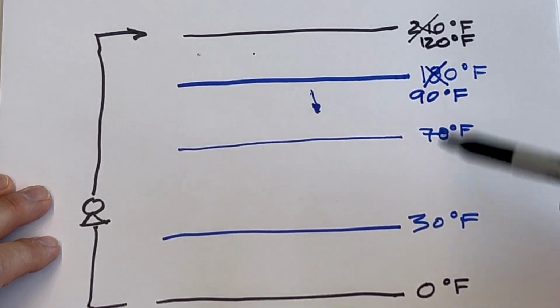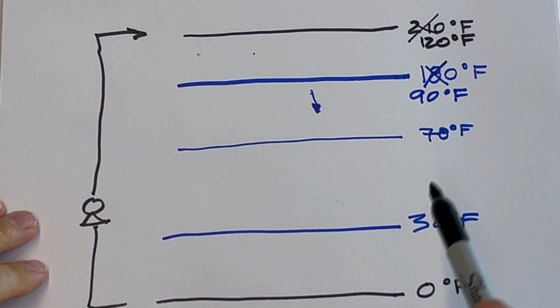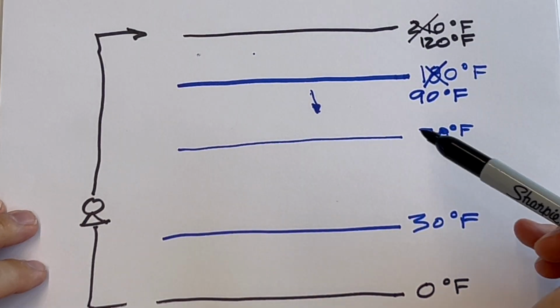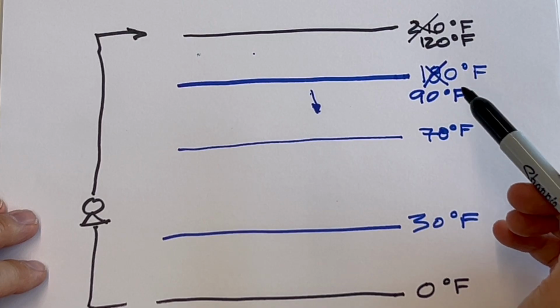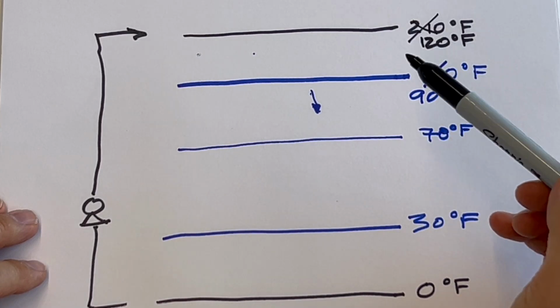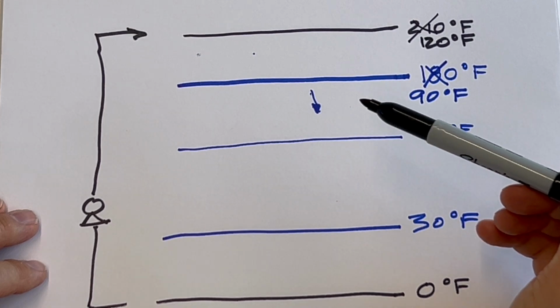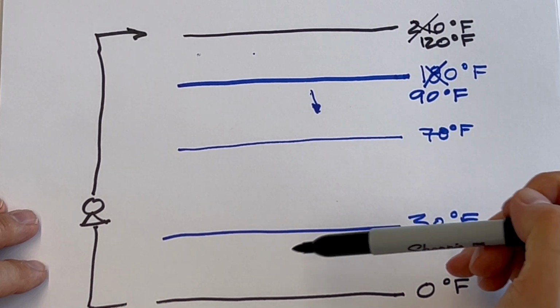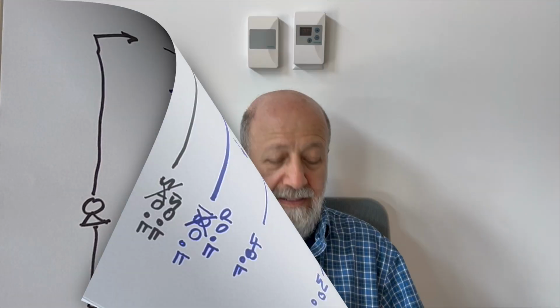That is a much lower lift. That heat pump will use substantially less energy for the same capacity as one that's replacing a boiler. It's why a direct boiler replacement with an air-to-water heat pump is such a difficult thing to do. Besides the availability of heat pumps being small, the power requirement is much greater.